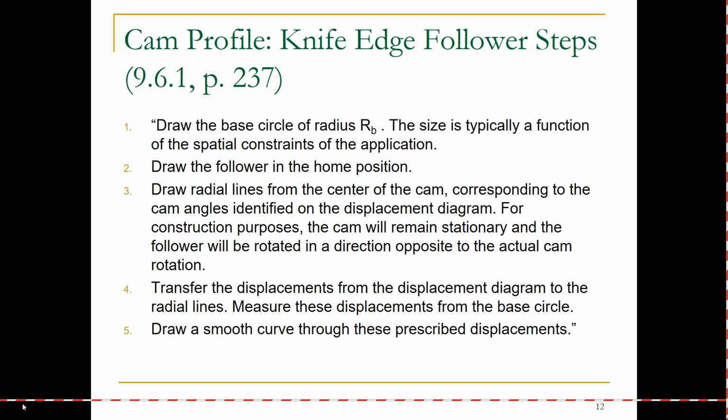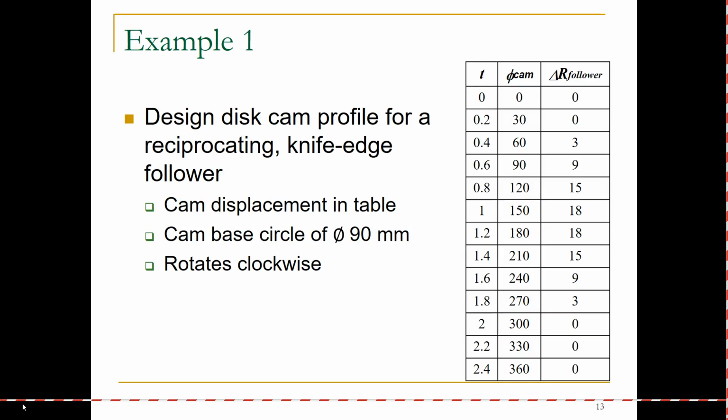to the CAM. Once we do this, we're going to connect those displacements with a smooth curve, and that will deem our CAM profile. Pretty easy to do with a knife edge follower, especially when it's in line. So let's get to it. So following along, if you look at example 1, this is what we're working through. And you can see here that we could look at this in terms of time or in terms of configuration,